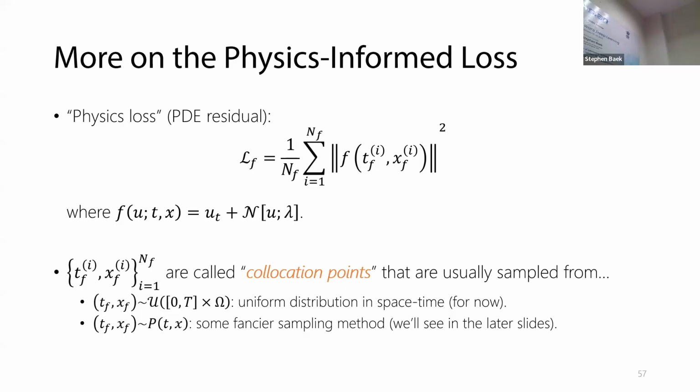So again, if you have a CAD model, for example, then you want to sample points inside of that CAD model if you're talking about some solid mechanical problem. Or if it is some fluid phenomena with certain boundary condition, again, you have to consider the geometry when you do the sampling.